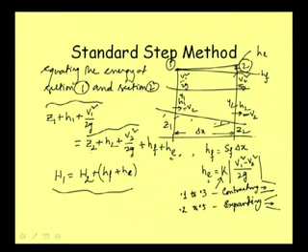If we are computing from the downstream side to the upstream side, say our first known point is at downstream and the unknown point at upstream, then this HF plus HE, that is the loss, we will have to deduct from here. Then only we will get the head here. That way we can use a plus or minus sign and write it accordingly.